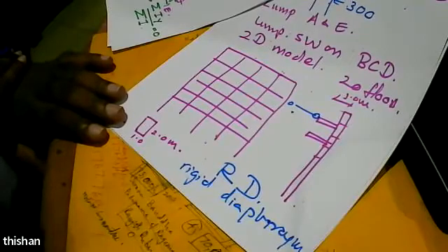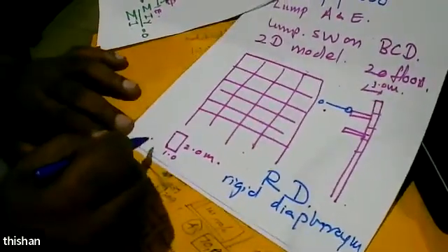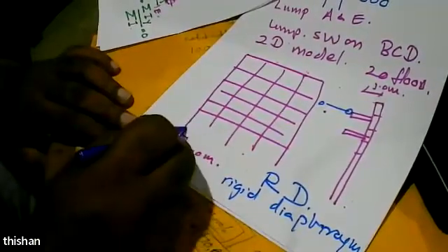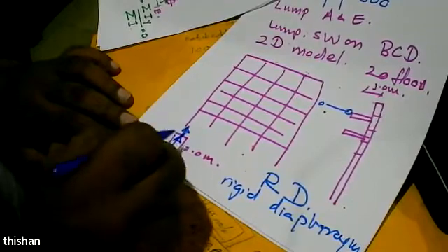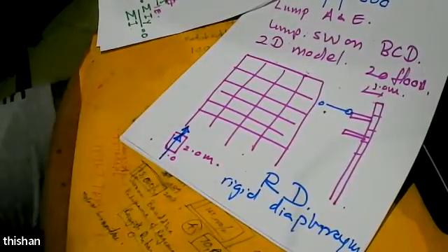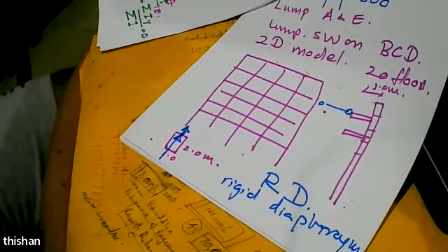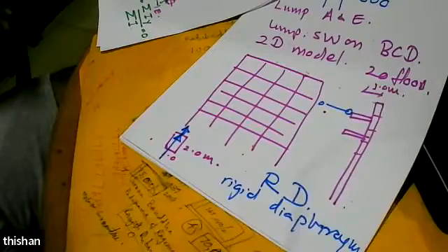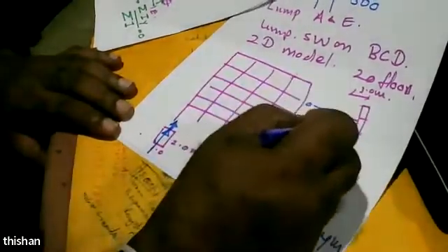So basically, you have a larger section here, 2 meters wide, but what is the axis of bending? The axis of bending is still that. So here what we find is the second moment of area has been doubled only. So you can have these corrections at every floor.